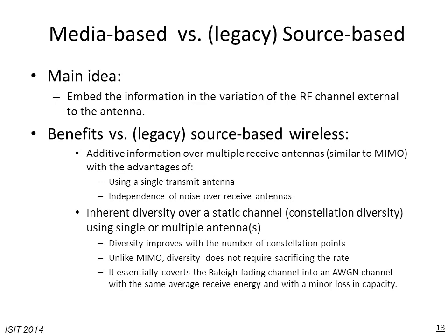Although later on I will come to this point, I would like to clarify here that when we have K parallel channels, we need to spend K units of energy at their input. However, in a media-based modulation, we transmit a single unit of energy over a single transmit antenna, and we receive K units of energy. So this feature of energy harvesting is another benefit that we get compared to having purely K parallel channels.